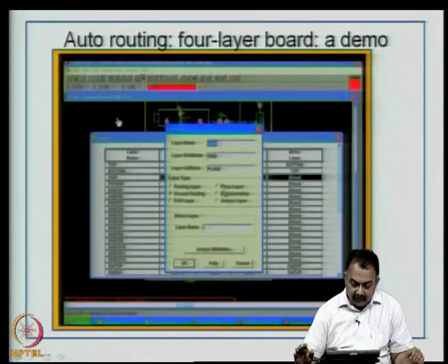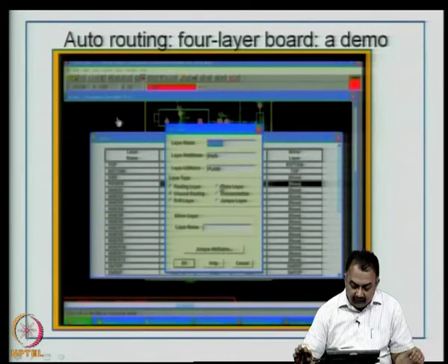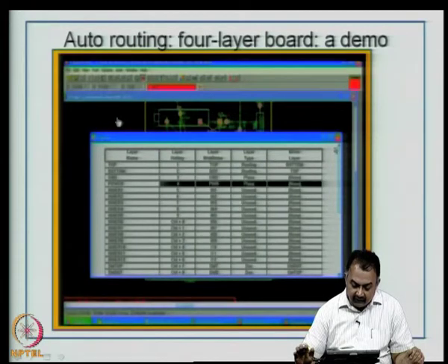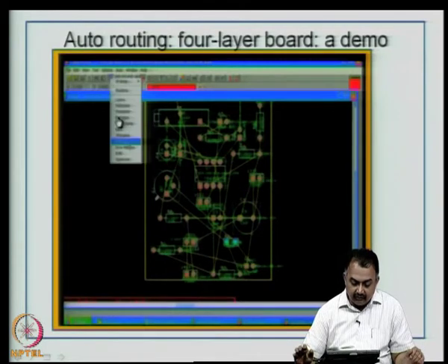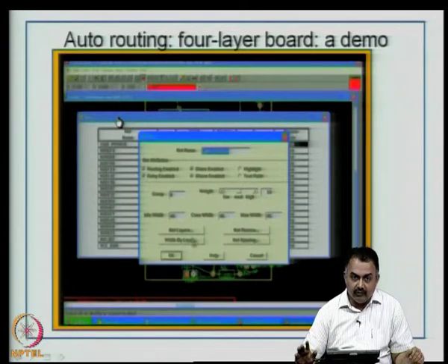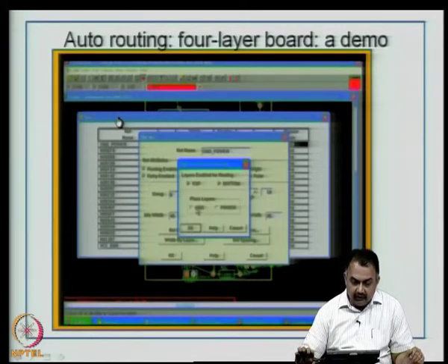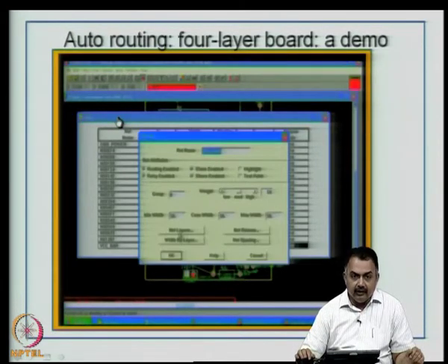So, you activate the ground plane that is required to be inserted, and then a power plane, which is again not considered an electrical layer. So, it is considered as a plane layer. So, you can also set the design rules, that is the line width to be used in those areas, and you can also name this particular layer as ground, power and so on.